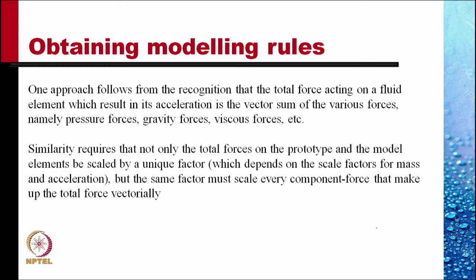One approach follows from the recognition that the total force acting on a fluid element, which results in its acceleration, is the vector sum of the various forces, such as pressure force, gravity force, viscous force, etc. Similarity requires that not only the total forces on the prototype and the model be scaled by a unique scale factor, which depends on the scale factors for mass and acceleration, but the same scale factor must scale every component force that makes up the total force vectorially.